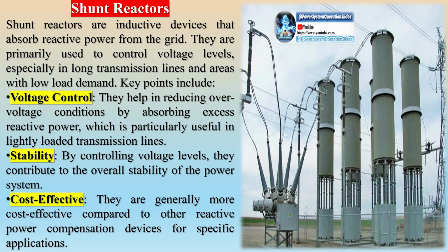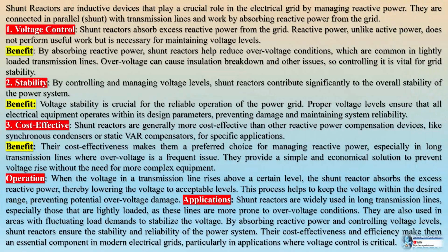Inertia contribution. These devices provide inertia to the grid. Inertia refers to the resistance against sudden changes in frequency. This is particularly important as the grid incorporates more renewable energy sources, which typically have lower inertia. The inertia from synchronous condensers helps stabilize frequency fluctuations, maintaining the balance between power supply and demand.